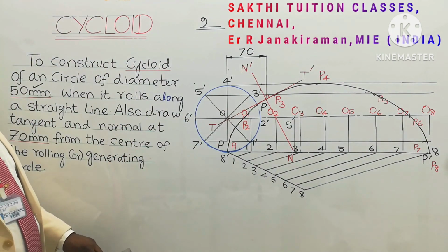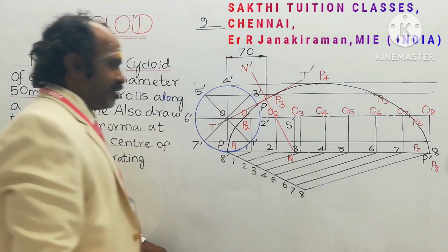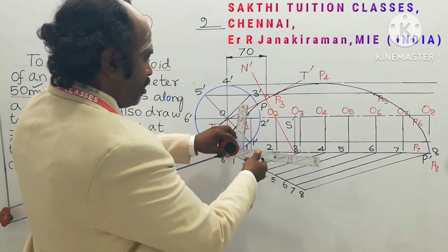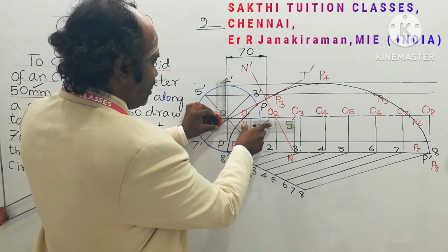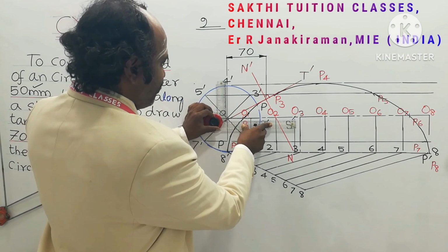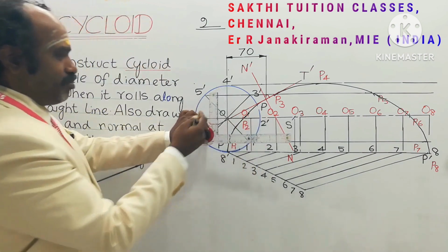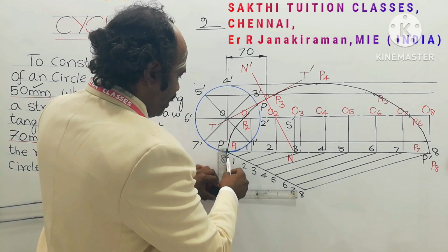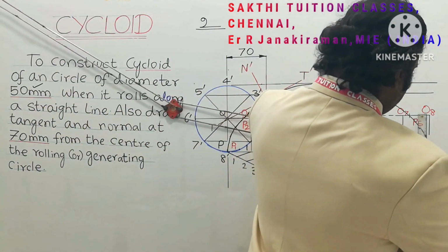Next, you have to dimension the circle and the length P dash. So reset your drafter scale. Release it by rotating anti-clockwise, and keep it on the first drawn line, which is a vertical line. Using the vertical scale of the drafter, the scale edge and the line should coincide. Then rotate it anti-clockwise, and the scale will be positioned like this. Draw an extension line from point P and another extension line from P dash.